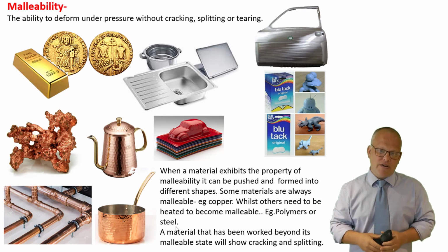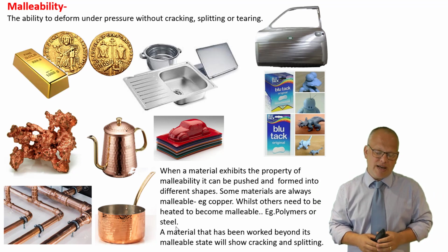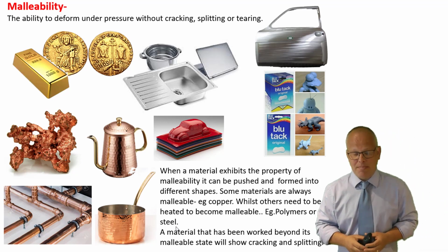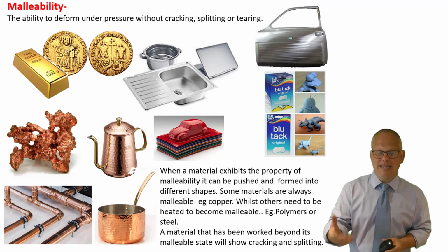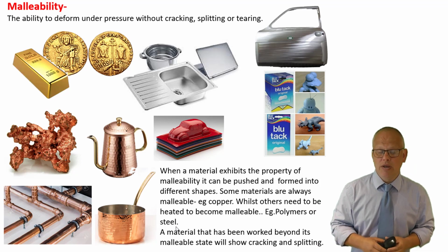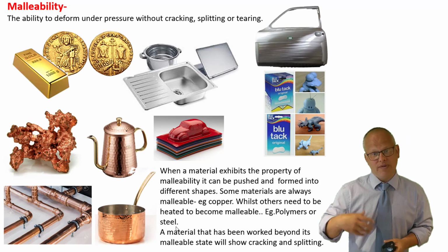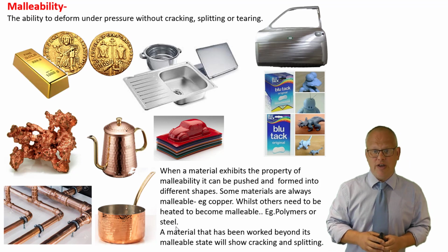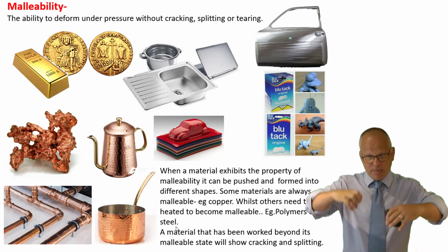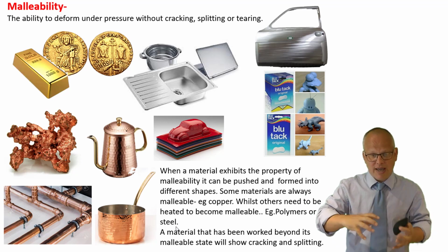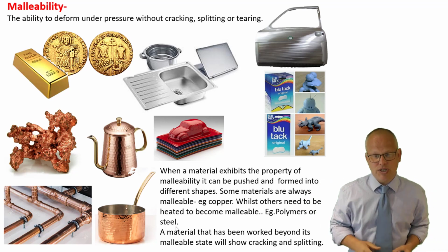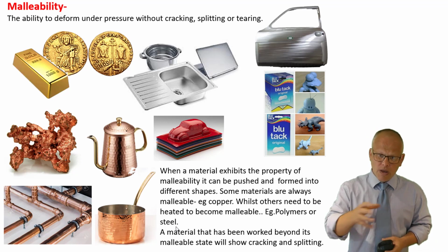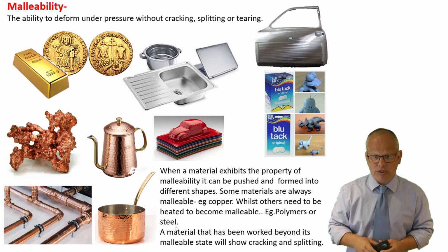I've given you the example there of polystyrene for the vacuum forming machine. Plastics can be malleable, but sometimes by heating a plastic up or a polymer up, you can actually make it more malleable. Particularly thermoforming polymers, such as polystyrene that I've shown you there, if you heat that up under the vacuum former, it becomes like rubber. It becomes incredibly flexible, and it can then take up the shape that you're vacuum forming it over. When it cools, it goes back to being a more stiff object.